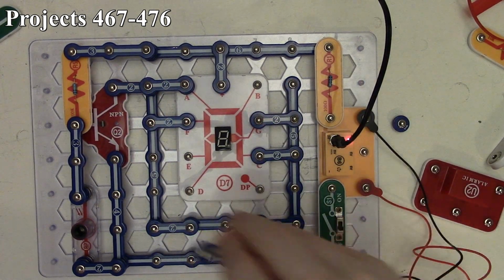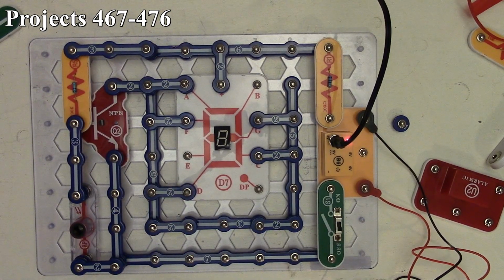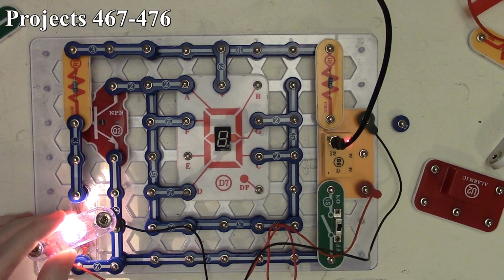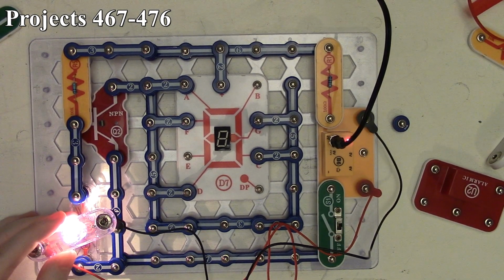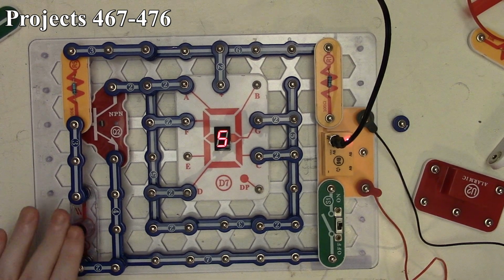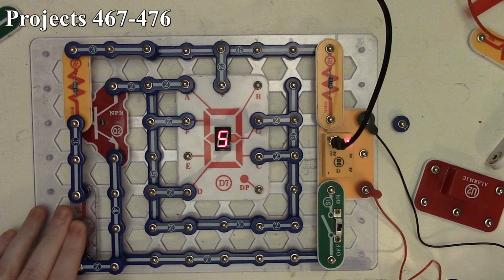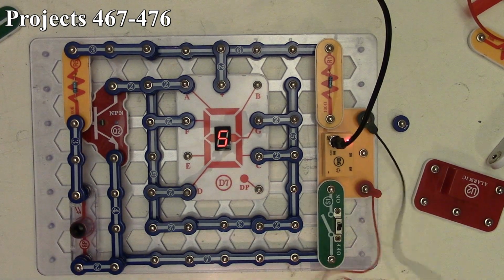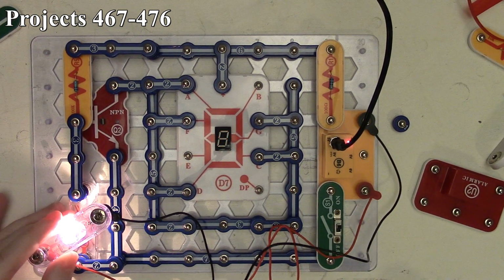G and D. Okay. Bring our light over, turn the circuit on. Again, nothing shows on display. Take the light away, number 5 begins to show. Cover up our photoresistor, gets nice and bright. Let some light back in, gets dimmer, bring our 6-volt lamp back over, and it goes out.